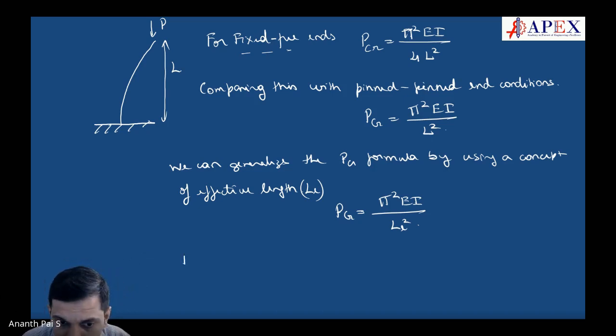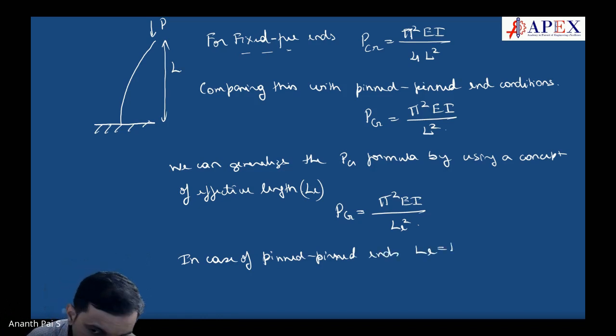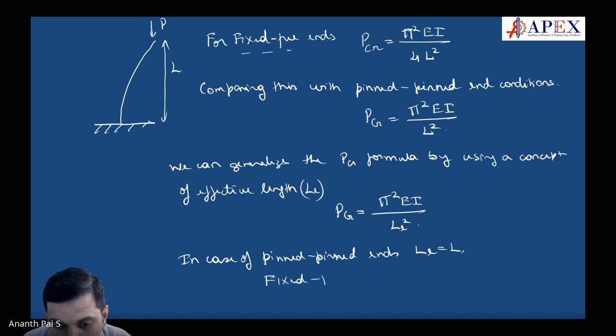In case of pinned ends, LE is equal to L. In case of fixed free ends, LE is equal to 2L.